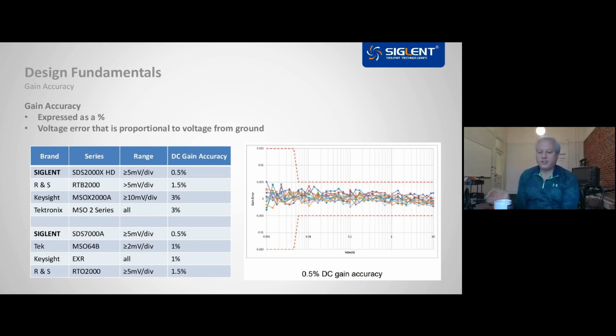On the right, you see a statistical analysis of channel ranges and gain errors on our instrument and how they fit well within that specification band. So you typically have a tighter band for higher ranges, and then often a little looser band as you get down towards the true noise level of the instrument. We'll depend on this accuracy to correctly analyze signals, especially when we need to stretch the capability of our ranges and resolution to capture signal artifacts.